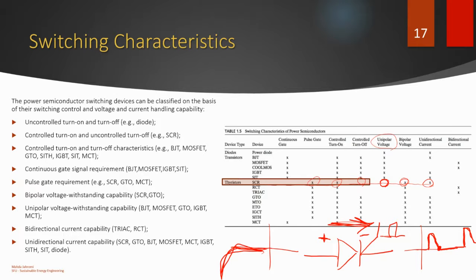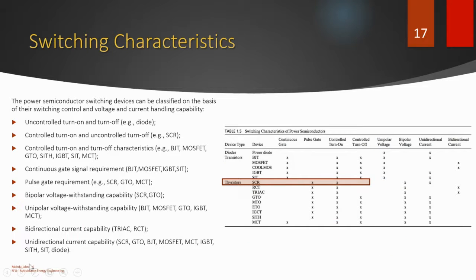And that's it. The other one that I want you to look at is this one. I think this bipolar voltage means AC. So this is for AC applications. This is for DC applications. So you can use thyristors in AC as well. So that's the AC-DC source that we were talking about. I think it's just a poor choice of wording, but that's basically what this means.